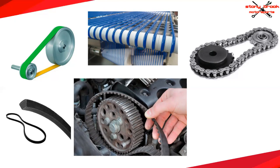Lastly, we have chains on the top right. Chains, as you see, again, are these metal links, and then they sit on sprockets which have teeth, and that's really how the power transmission happens. The reason why these are good for longer center-to-centers is that you're able to make these belts or chains generally fairly long.